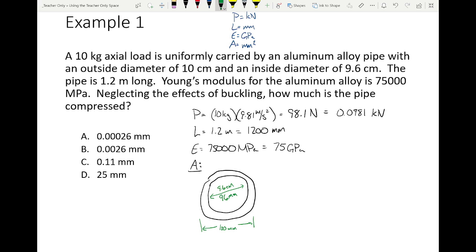If I go to Lowe's and I buy pipe, how am I going to go to the customer service rep at Lowe's and say, I need a pipe with a 3.75 inch radius? No. How are pipes expressed? In diameter. How are bolts expressed? Diameter. That's just how terms are expressed. And so understanding how to compute area in terms of diameter will save you time, especially on an exam like this. So if given the diameter of a circle, the area is pi d squared over 4, right?